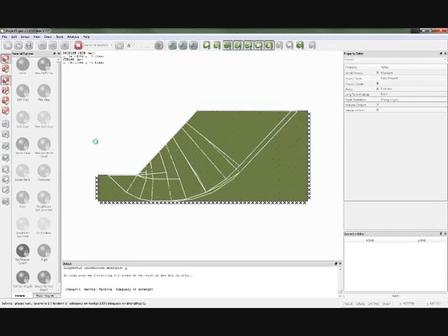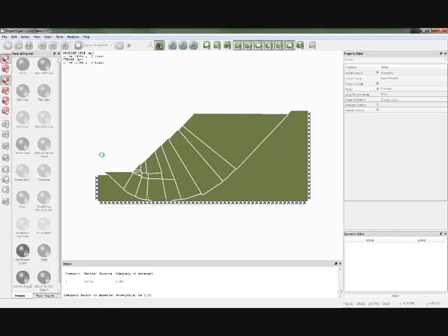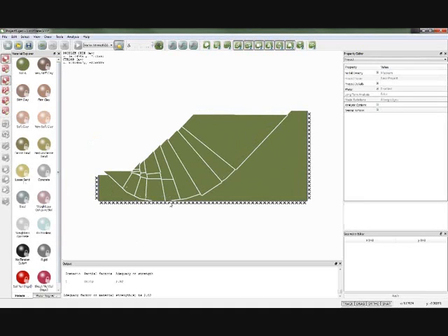Now, for those of you familiar with this type of analysis, you'll realize we're onto a sort of road to nowhere here. I can keep pulling these boundaries out forever, and for slopes that are shallower than this angle or this angle, the actual critical mechanism is effectively of infinite size, but the factor on safety doesn't change that much. So if I kept pulling those boundaries out, the mechanism would just grow and grow, and that's what you see from the Taylor analysis also.